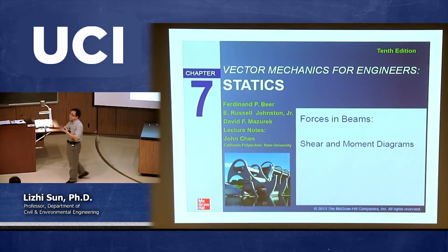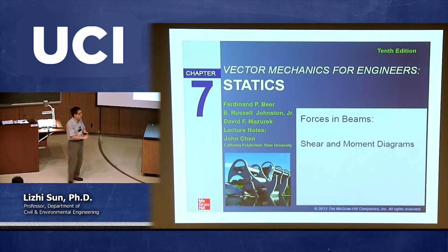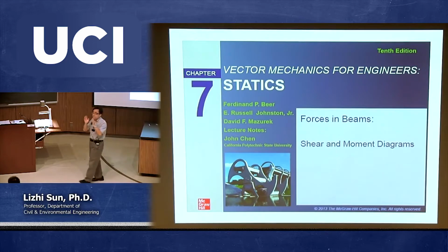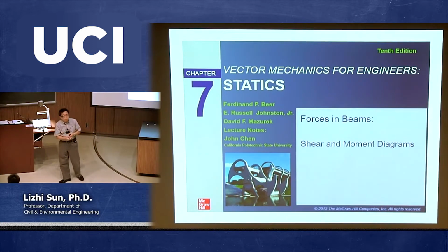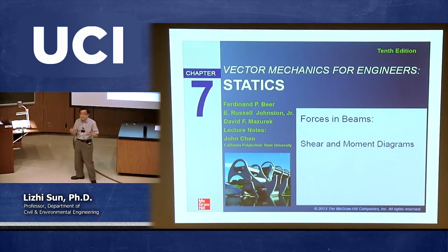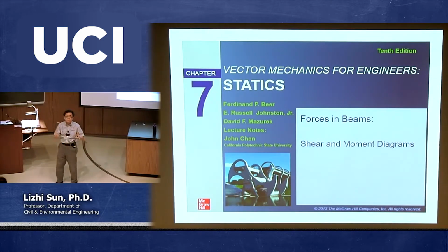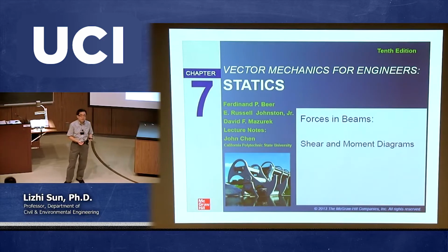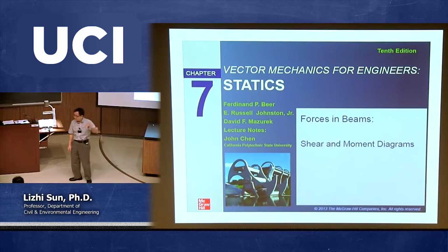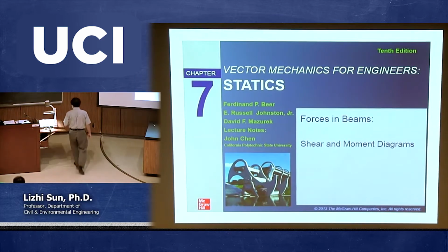After we identify the minimum number of cuts, then in each segment we need to build up those two important equations, allowing us to calculate the shear force and the bending moment as a function of location. And finally, we plot those two functions. That's supposed to end that given problem.